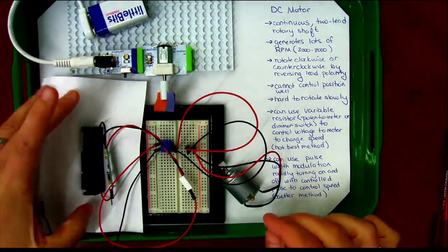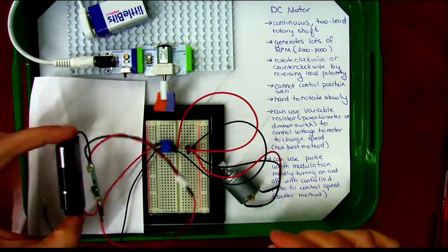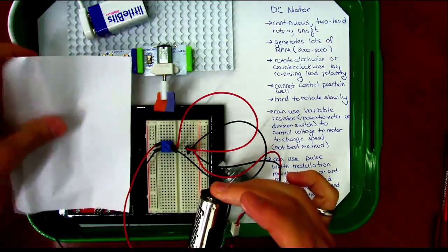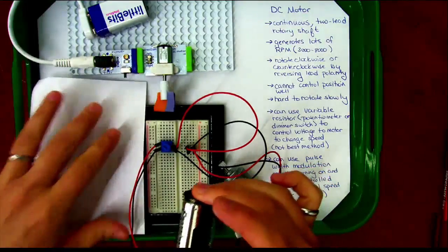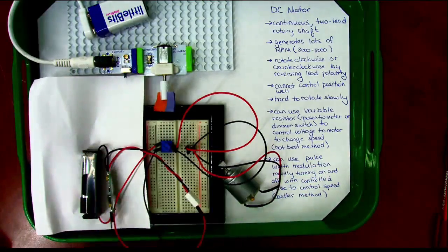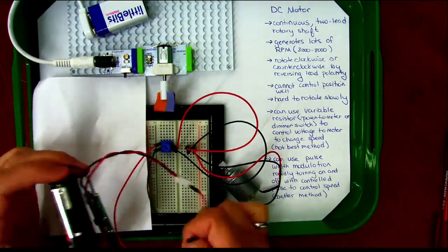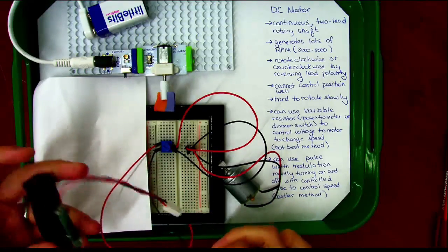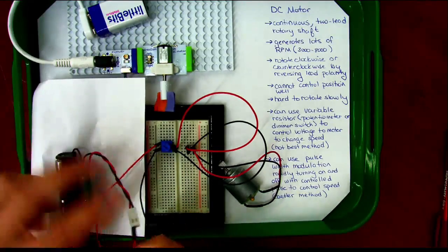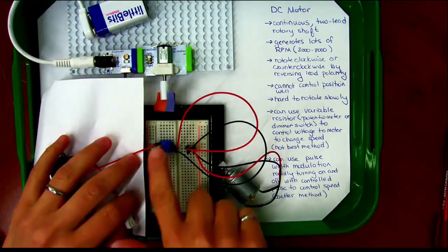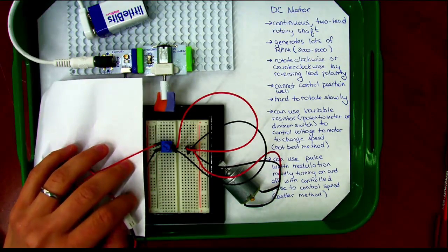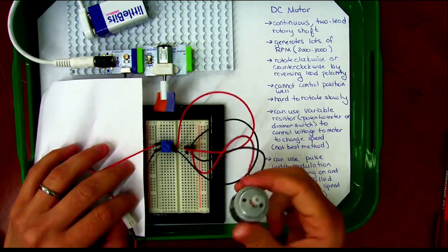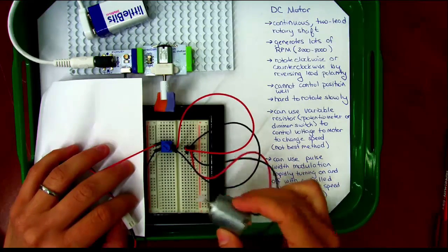So DC motor, I brought a couple for you guys here. This one, I covered up the board because I'm not actually using the SparkFun program, but this was already stuck down, so pay no attention to the stuff under the paper. I just got a battery, and it has a little circuit to bring it up to 5 volts that it's delivering out. It goes out to 2 wires. I put my potentiometer in the middle so we can control the speed by reducing that 5 volts down to some proportion that then goes out to our little DC motor here.